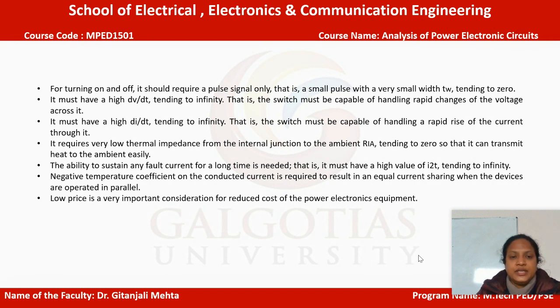The ability to sustain any fault current for a long time is needed, that is, it must have a high value of I squared T tending to infinity. Negative temperature coefficient on the conducted current is required to result in an equal current sharing when the devices are operated in parallel. Low price is a very important consideration for reduced cost of the power electronics equipment.